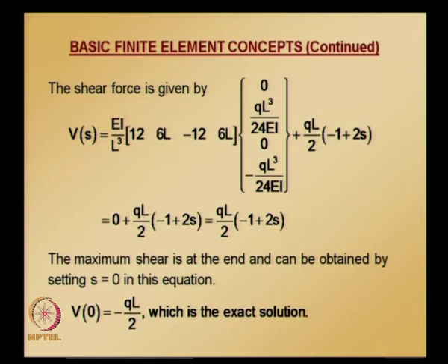So, once again I want to emphasize the procedure of this superposition method: proceed in the usual manner of writing element equations, assemble them to get the global equations and solve for the nodal unknowns, and then when computing the element quantities, the exact solution of the fixed end beam problem is added to the finite element solution. So, this is the procedure.